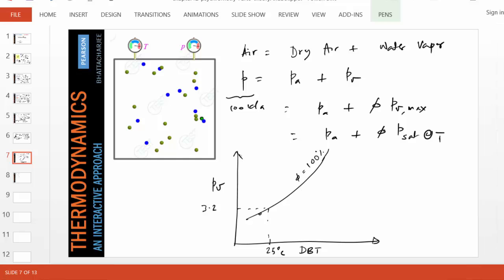So this is also known as the psychrometric chart, where you understand that the vapor pressure in air can never be beyond PV max. So the state of water vapor in air will be somewhere in this area. So the psychrometric chart looks something like this, where the phi equals 100% line looks like this. So suppose the question is, how will a phi equals 50% line look? At a given temperature, we can quickly say this is the maximum PV.